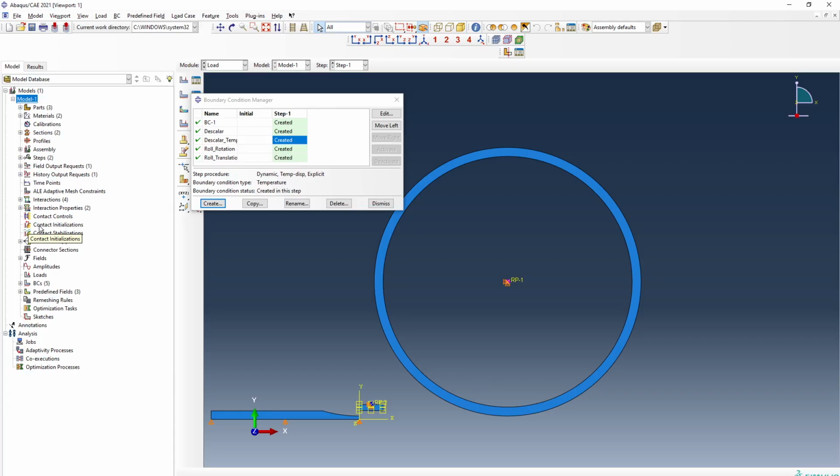So I think the initial conditions are prescribed, the initial temperature, initial velocity, and then thermal boundary conditions and the displacement boundary conditions are prescribed. Fine, thermal we can do one more thing, which is the normal heat flux is 0, but that is anyhow the default boundary condition, so I'll leave it at that.